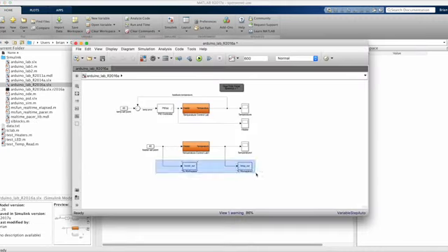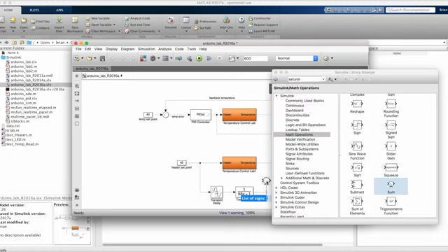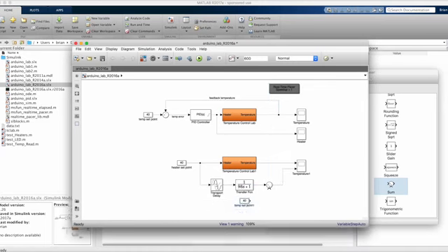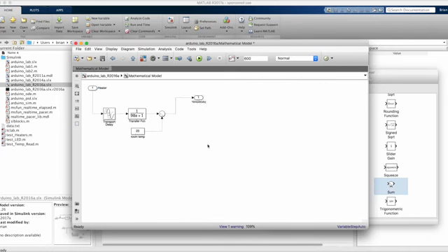Or since I'm working in Simulink, I can just build it there as well. Now this is just the dynamic portion of the system, and if we inputted a 0 for the heater, the output of the system would also be 0 for this transfer function. But we know 0 input means room temperature output, so we have to add a constant room temperature value to the output to create our mathematical model. And there we have it.